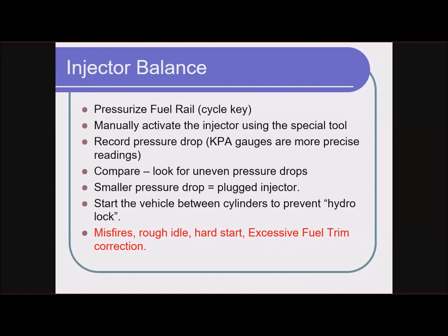The instructor did the demo and then had a student do it, and then had another student do it, and then another student do it. Every time this test runs, fuel is spraying out of the fuel injector into the engine. After several students did this test without running the engine, when they tried to start the vehicle, there was so much liquid fuel in the cylinders that it actually bent connecting rods. You can compress a gas, but you cannot compress a liquid. That's known as a hydrolock.